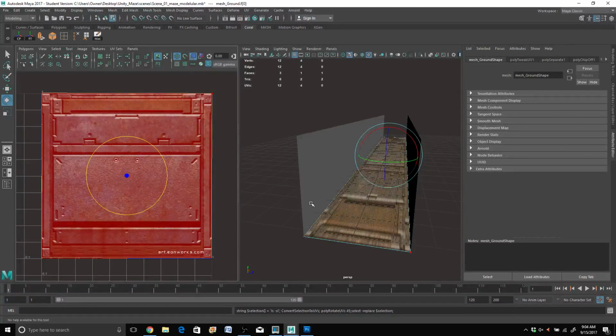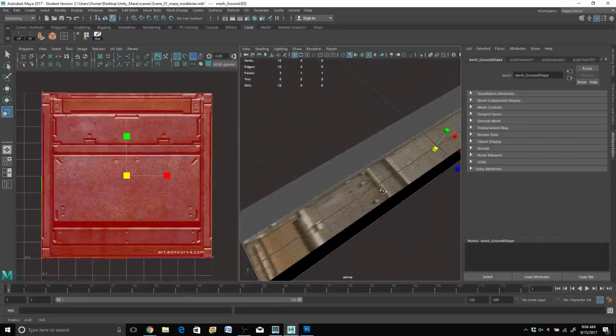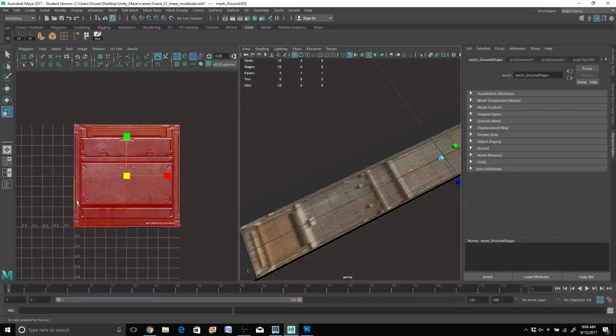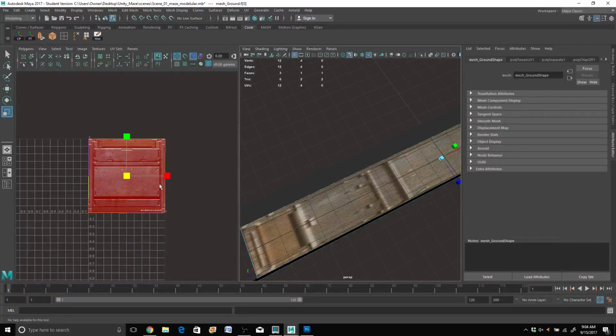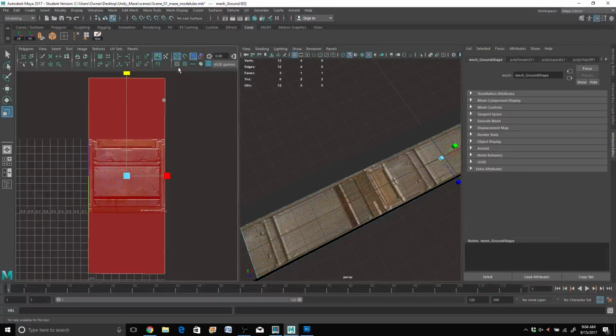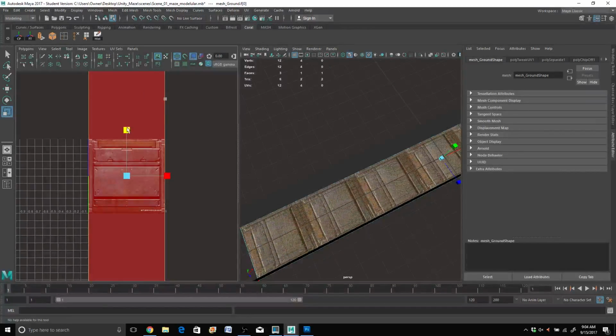Okay, so that's the way I wanted it, so that I can look up over here, and this whole thing looks like it's stretched all along here. Perfect. Now, it's still stretched, so I still got to fix that. Something you want to know about these UVs is that even though you can't see this texture anywhere but this 1x1 area, this goes infinitely in all directions. So all I have to do to make it tiled and look a little bit more visually pleasing, not stretched like that, is just scale it, and it'll continue to keep pushing out more floor tiles till it looks right.